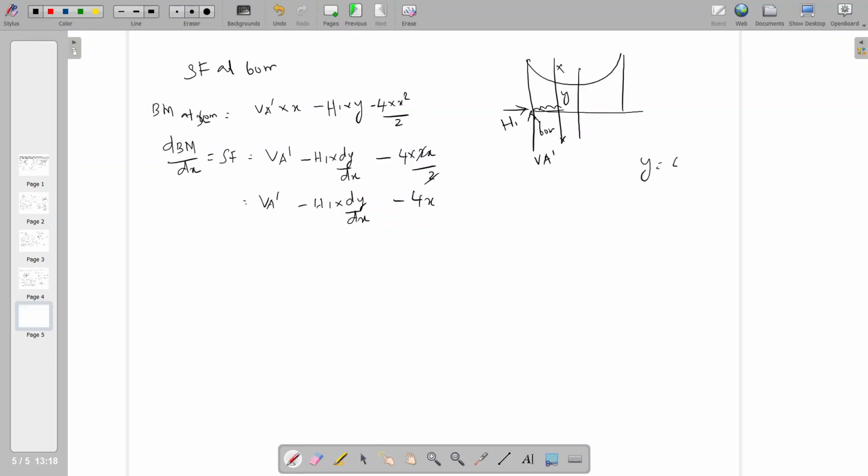The y equation is 4yc by L square into x into L minus x. So 4yc by L square; if you differentiate with respect to x, L stays one time, and if you multiply it inside, it is x square, whose derivative is 2 times x. So 4 YC, the tip of the cable, is 25, by L, which is 200, square, into L which is 200 minus 2 into 60, our first section distance.